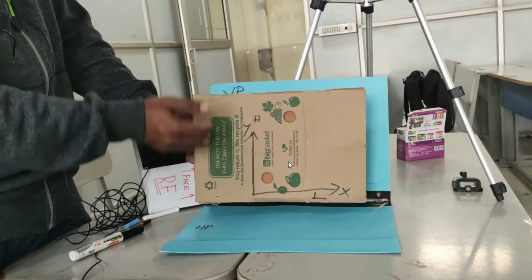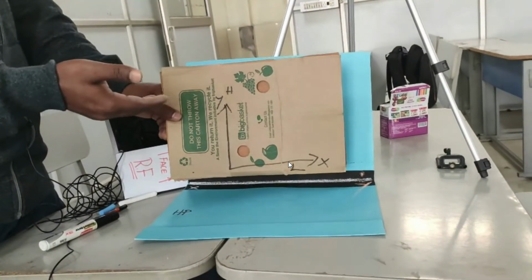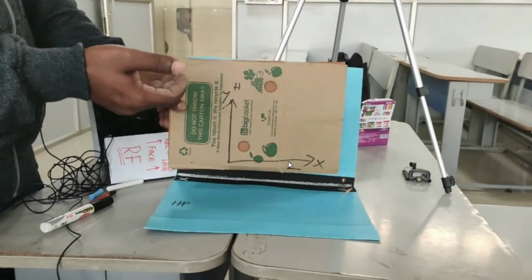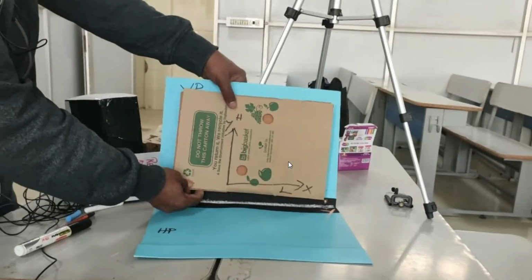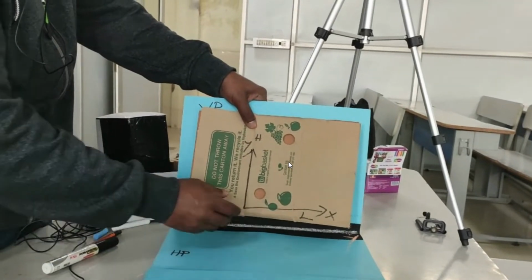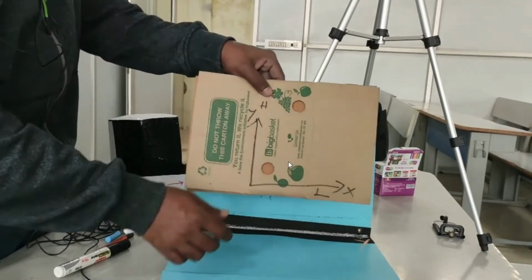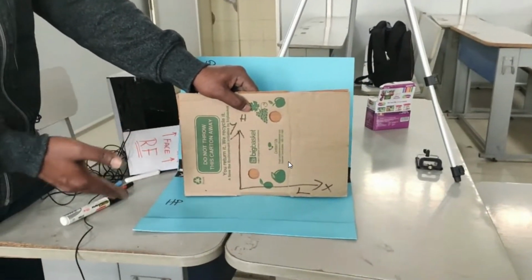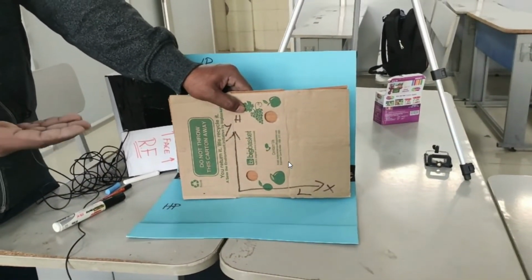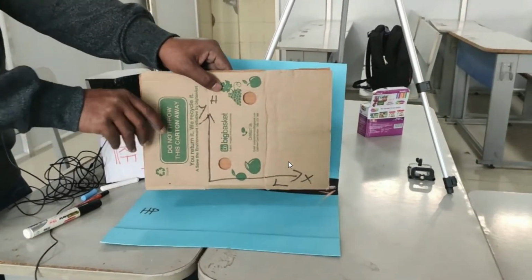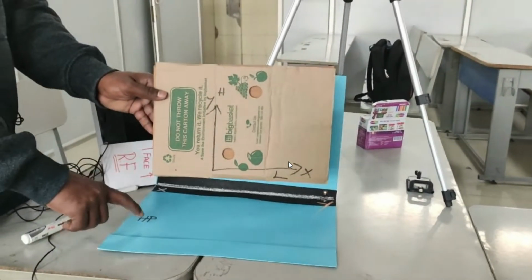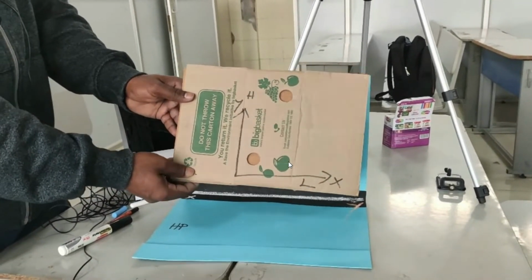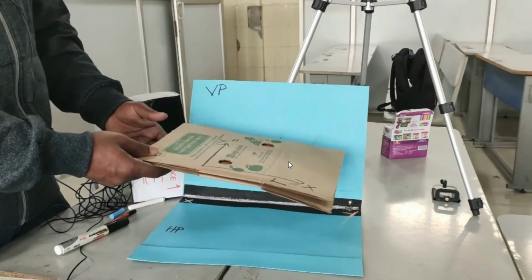So you will get height in the front side view, and length you will get as well. The shadow is going to project on the VP plane. Now you can see it is parallel to VP. The same line, you can see, is perpendicular to HP, and it is parallel to the VP plane. So this is the first case that I want to tell you. Sometimes they will say some height above the HP plane. In that case, the height will be over.